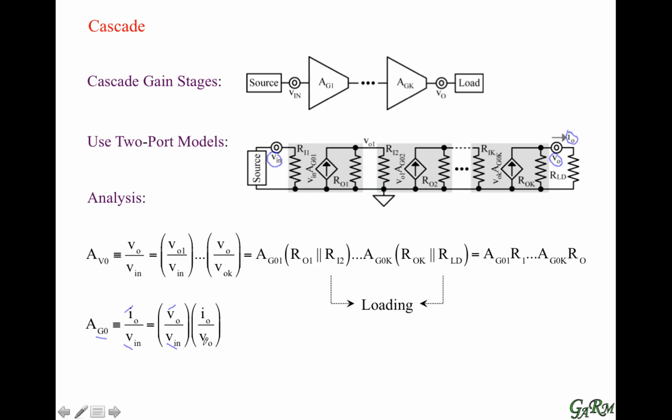And then we do a small signal gain translation from the output voltage to the output current. We know the gain translation from the input voltage to the output voltage is the voltage gain that we just did in the previous step. So we can use that, and we know that the small signal translation from output voltage to output current is nothing but the ohmic translation across the load resistance.